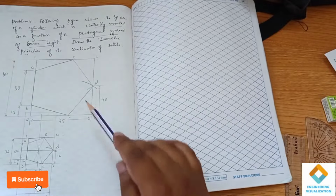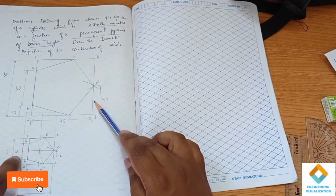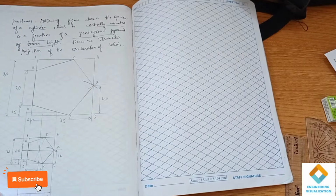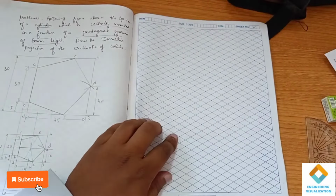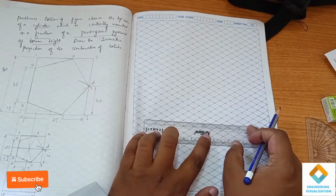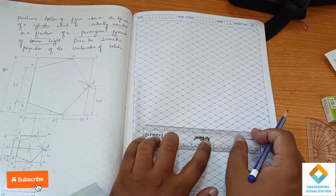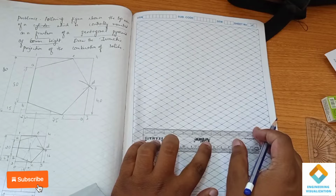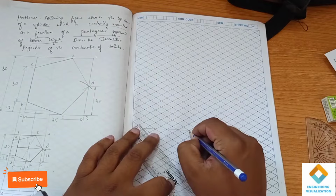orthographic of it. So herein I have drawn a pentagon of dimension 50, another pentagon of dimension 20. Okay, so above it I have placed a cylinder here of diameter 40. You can see it. So first I am constructing this pentagon. Okay, here because it is a frustum, so herein I will draw a reference line here.